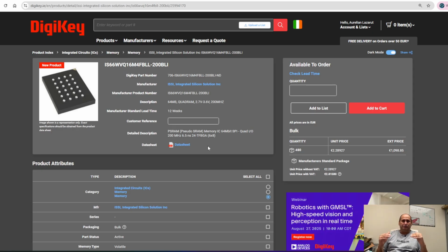And what's the penalty? You want to access the memory, and the memory internally is in a refresh cycle. In that case, it will add to latency. So basically, the memory will tell the controller, the FPGA in our case, hold on a little bit, I need to finish my refresh cycle. This is called a collision. So you can read without a collision, if you're lucky, or with a collision, if you're unlucky.